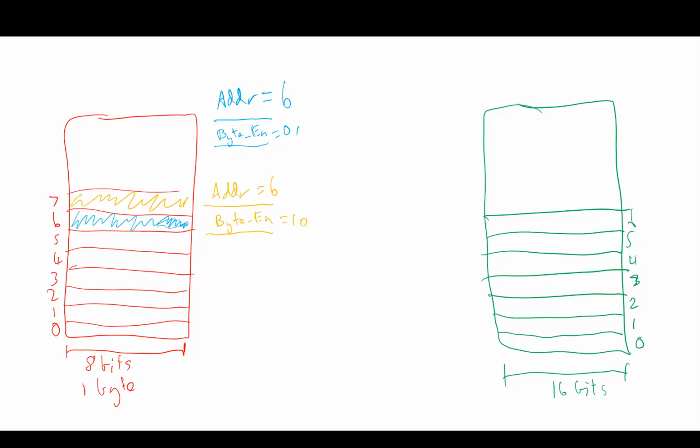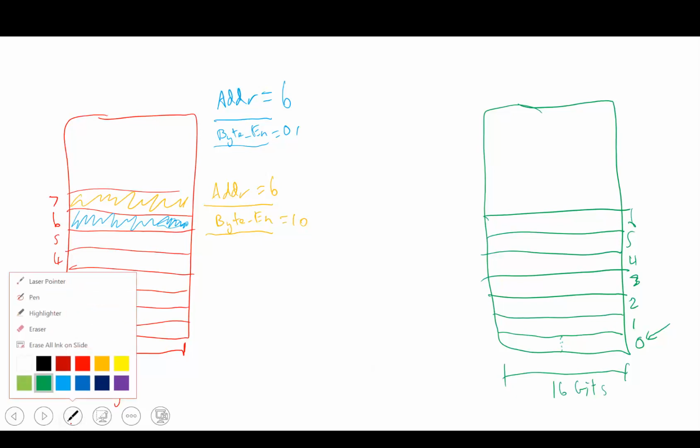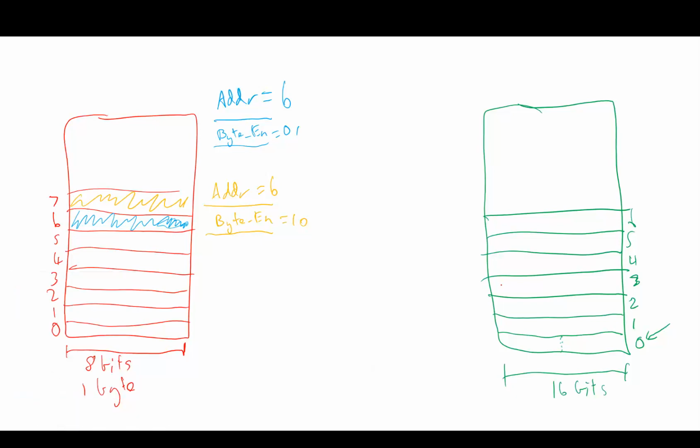So this is address 0 in the SRAM chip, which refers to the address of this half word. So you can imagine there are 2 bytes in there. So in order to access, let's say this half word, the address line here would equal 3.